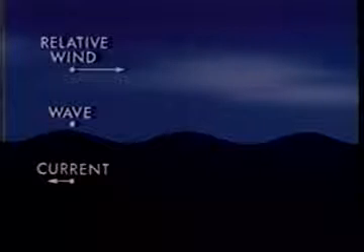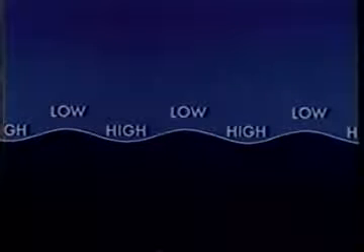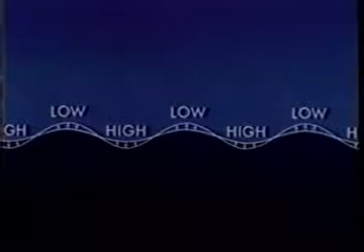The pressure will be low at the crests and high in the troughs. This distribution of pressure tends to increase the wave height, were it not for gravity and surface tension, which tend to flatten the waves. In this simplified view, if the pressure forces win, the waves will grow and we have instability. If gravity and surface tension win, the waves will decay and we have stability. This does not explain how we get energy transfer from the wind to the waves.